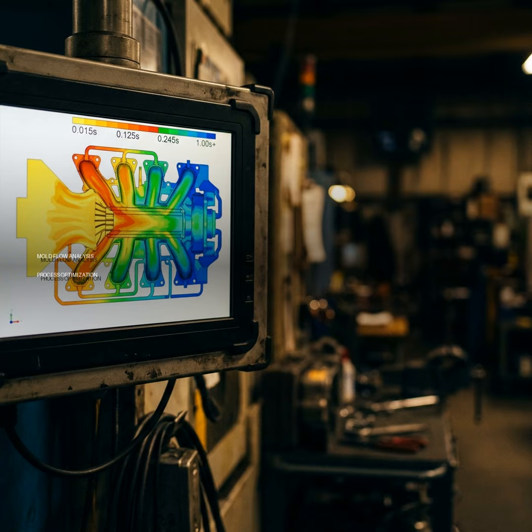All that data is critical. That makes sense. The plastic's properties are everything, aren't they? Then you move to the actual process settings, I assume? Yep, process settings. You've got two main modes in most software: CAE mode, which is for preliminary evaluation without considering a specific machine, and injection molding machine mode, which is for later validation, where you can input actual machine parameters.